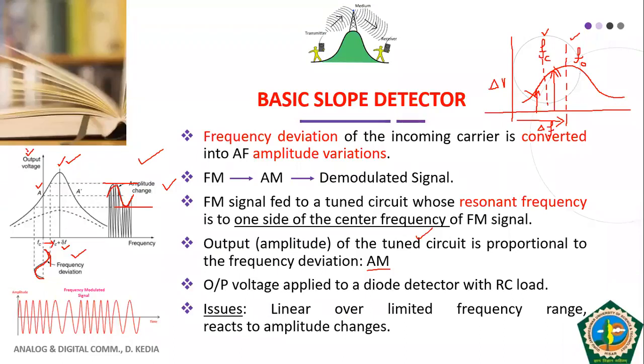Okay, this output voltage is the output voltage of the signal which is coming out. And which signal is coming out? The signal centered around the carrier frequency is coming out, and see, its amplitude is changing. Okay, and you can see this output waveform. It is nothing but the envelope of your carrier. Okay, and which can easily be demodulated with the help of your diode detector.